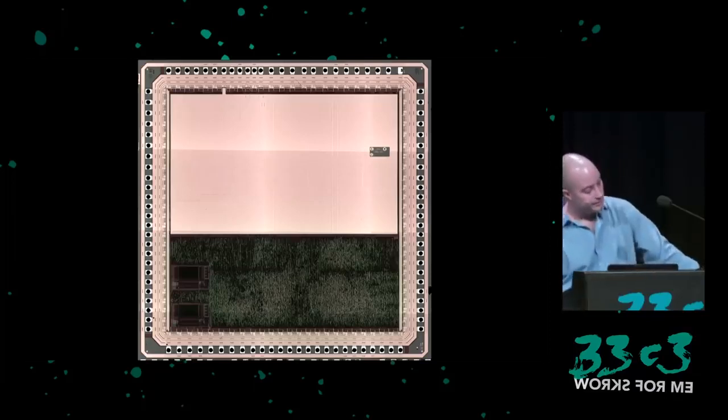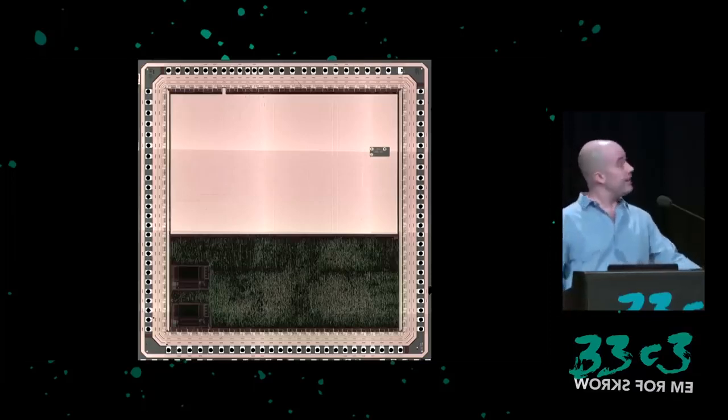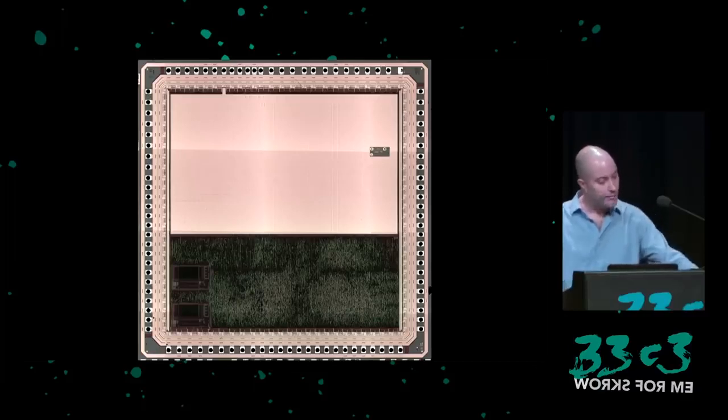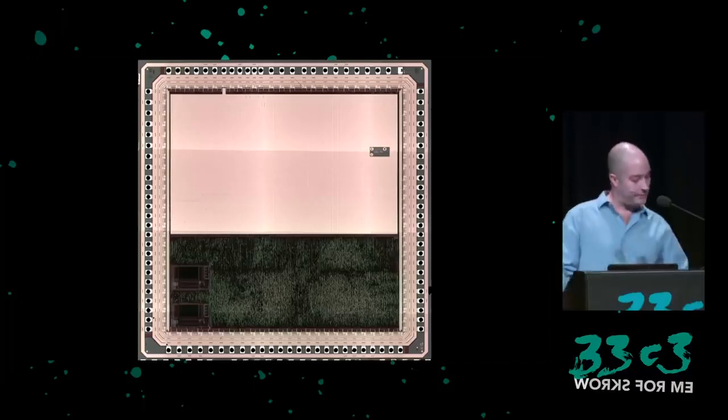This is an image of the chip under the microscope. It's been stitched together from several smaller images to give an overview of the chip. Looking at the decapsulated chip, we see the bond pads around the outside, a metal plane covering the top part of the chip, and on the bottom of the chip, the spaghetti logic running all over the place, with a couple of structures that look like they could be a type of memory. There's a lot still hidden from us. To see more of the chip, it will be necessary to delayer it.